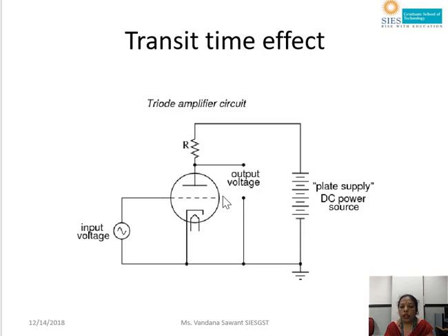But what happens if the electrons are emitted from the cathode and by that time the grid voltage changes to negative? The grid itself is negative, so it will not accelerate the electrons. Instead, it will reflect them. Because of the negative voltage, the electrons reaching the grid are reflected back towards the cathode. The cathode is also negative, so it is not going to catch those electrons; it will reflect them again back towards the grid.